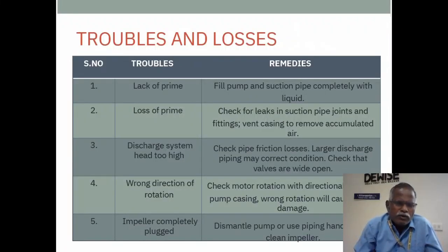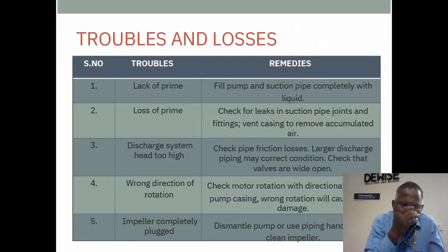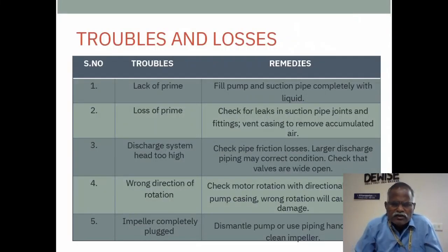If the valves are wide open, the cause may be the wrong direction of rotation. It may also be somewhere else. Check the motor rotation, clockwise or anti-clockwise, using the directional arrows on the pump casing. Wrong rotation causes pump damage.